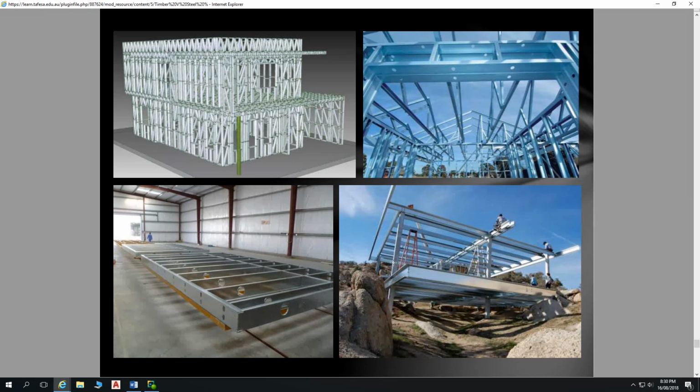And typically when we have very large window openings like this, those frames need to be very rigid, because we have very little tolerance for movement of those frames when we've got glass in between. We have some tolerance because we've got gaps between our window frames and that framing, but very little in percentage terms.